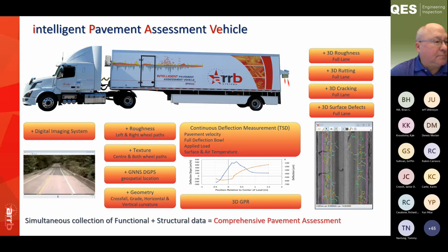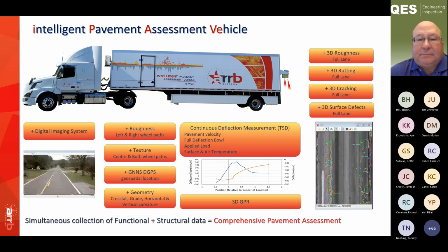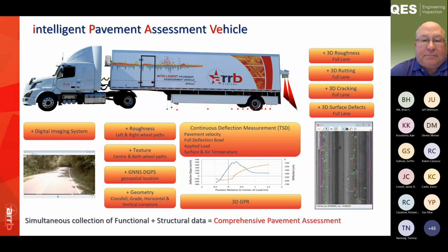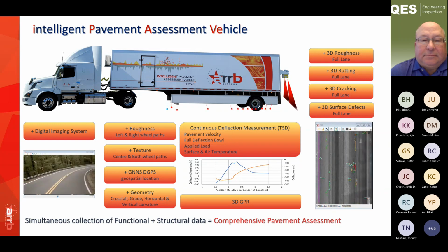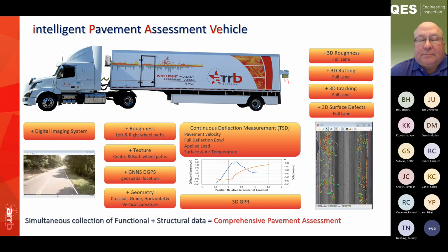One of the outcomes from that pool fund study was that it would be cool if you could add GPR to the truck, because it would help complement some of the other data streams. In fact, as you'll see in a little bit, we have now added the Contour 3D GPR right where the dolly wheels are in the middle of the truck, so that we can collect it along with the other structural response, all the surface characteristics, and the right-of-way imagery, so that you have hopefully all the information that you need to make an informed decision.